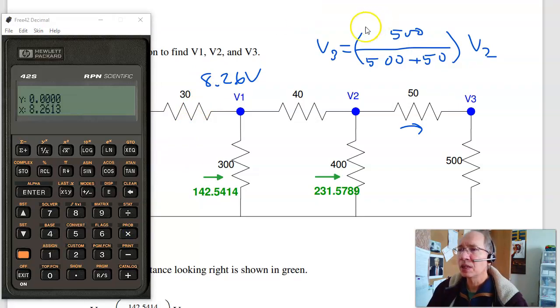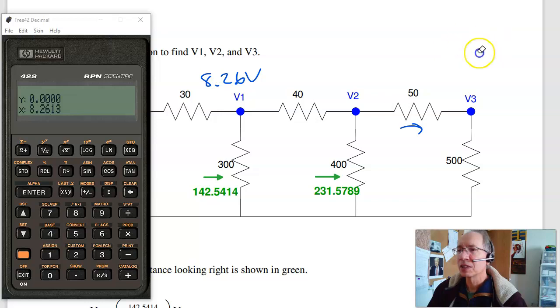Now, let's find the voltage at V2. And again, I'm going to show off how nice the HP calculators are. Erase all this. I'm going to take what I'm measuring, recall 02, that's why I saved it. Enter, enter, plus 40. There's your R1 plus R2. There's the R2. Take the ratio, and lo and behold, there's the previous answer. That's what's nice about the stacks. They record the old ones. Multiply. 7.04 volts.